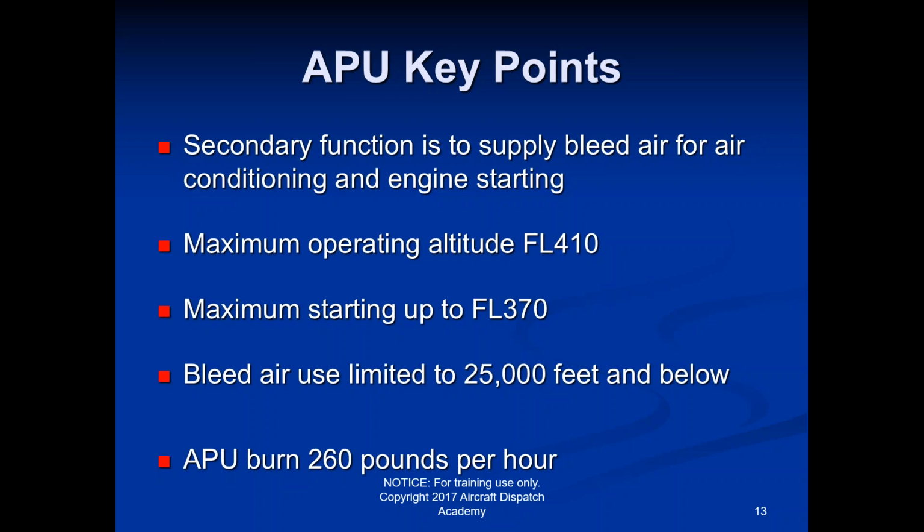Now, you might have a situation which is just causing everything, if you're flying through volcanic ash, it's going to be affecting all engines. But aside from that, if it was an internal problem in the plane and this one went out and then this one went out, those problems aren't necessarily going to be related to each other at all. But in order to lose electrical power, you've got to have both engine generators go out plus your APU, and then even if that happens, the last line of defense is they have this little thing.